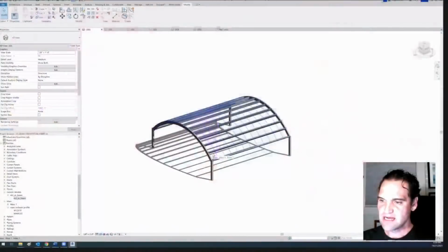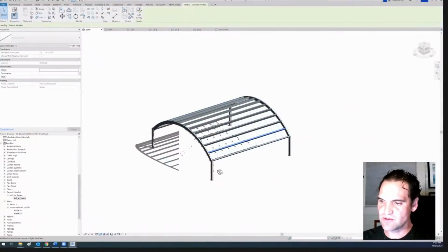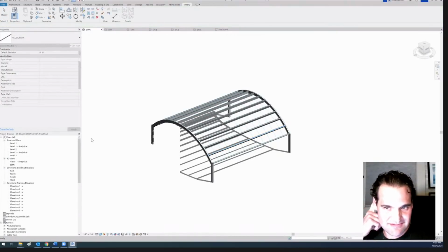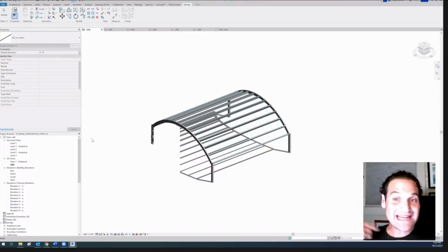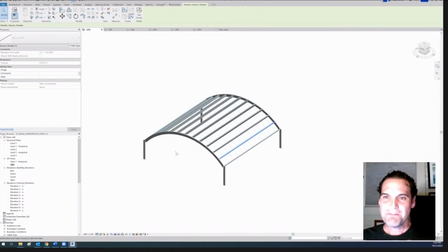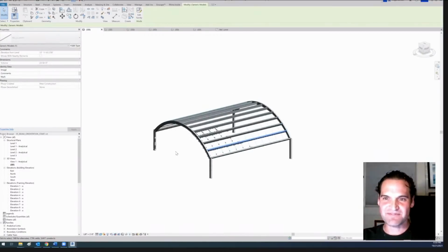I used to do that, Jeff, which means I would take this beam and put it into a category I was comfortable with. I would edit it as well so it looked correct in my documentation. That was so 2018. What I do now is I have come up with a more elaborate Dynamo script that mimics the adaptive component behavior.